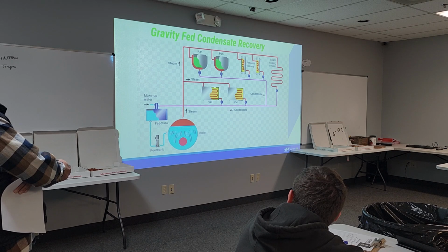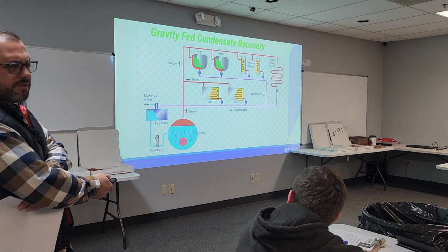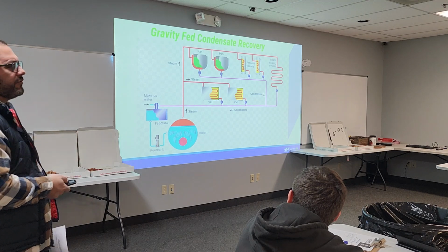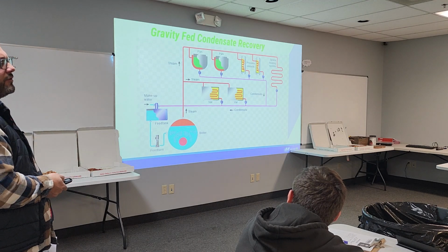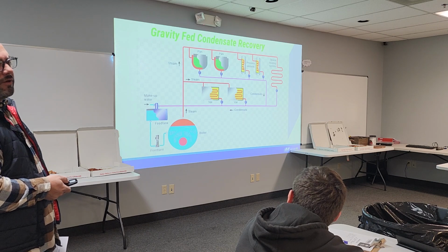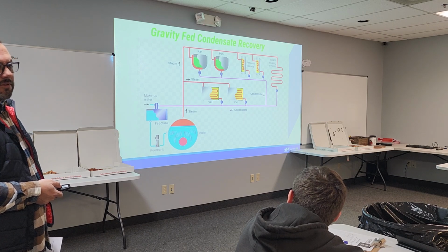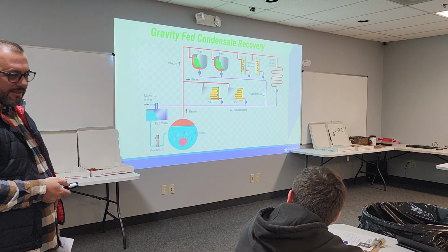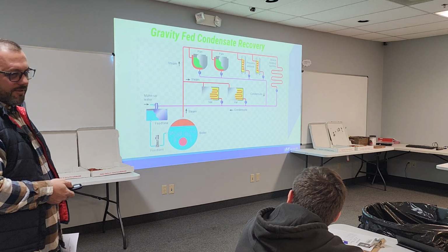In the case of steam coils, you guys probably deal with some steam coils. Recently at a chemical plant that I've called on for a lot of years, they've got 2 separate coils and they're trying to drain those with one trap. Doesn't work out very well. One of those coils is going to win. And what does the loss look like?